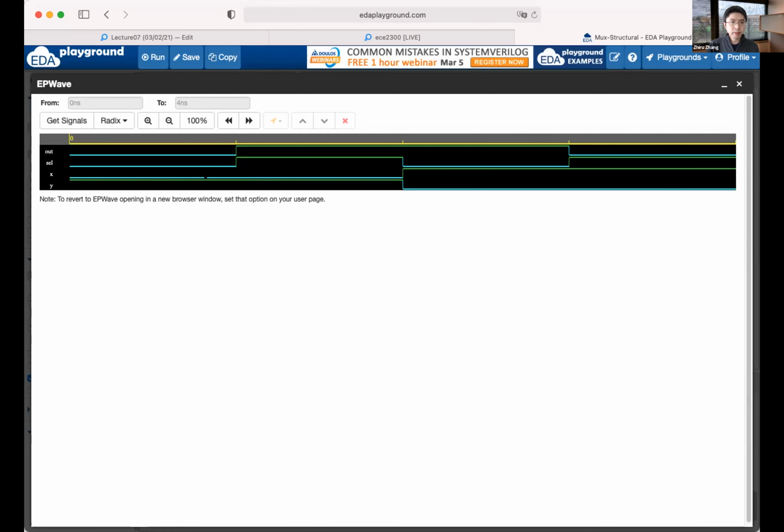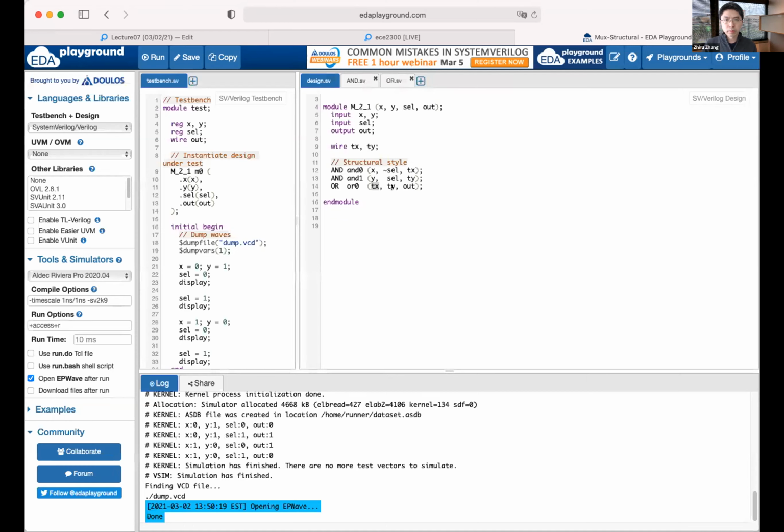It's a basic mux. We are implementing a mux using this Verilog code. Over here we have two ANDs and an OR. The tilde is doing inversion, so that we don't have to instantiate another NOT. Just for the sake of simplicity, this is the structural form.